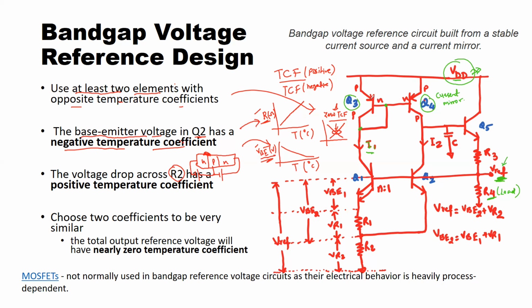And so I have this P terminal, N pin, and another P pin. This is the collector and this is the base. This is an emitter pin. So I'm making the base and collector short together so that this transistor Q3 will always be biased in an active mode, which is the linear region. Okay. And now I generated I1